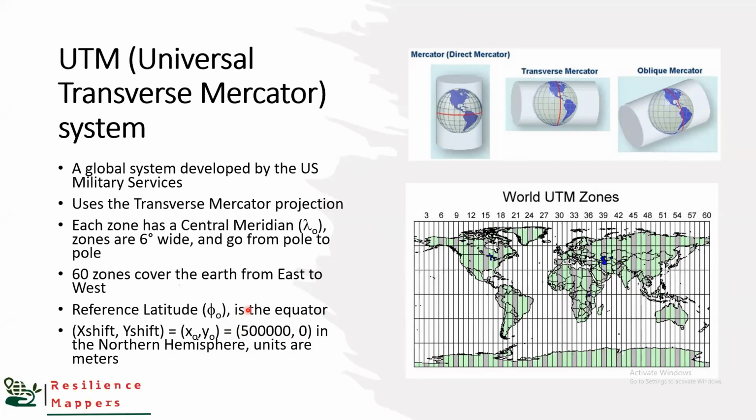Another concept that I think we need to explore is the concept of datums, which could also be considered a reference frame. For example, you hear a coordinate system like WGS84, and then you also hear WGS84 UTM zone 36 north, then you hear Arc 1960 UTM zone 36 north. Those are the different datums that are used in GIS.